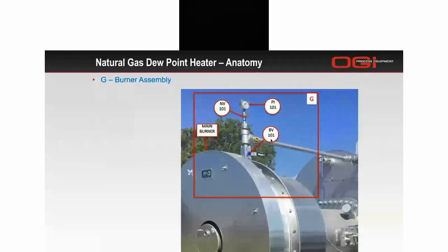And we've got a ball valve, BV101, at the very tail end. If you recall, there's also a ball valve right at the very beginning. So we've bookended our fuel train at the very beginning and very end with a ball valve. And again, this one is in the closed position, presumably for shipping purposes.